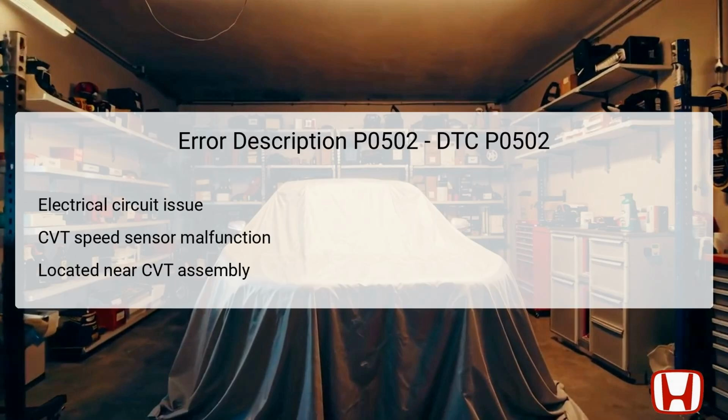The error description of DTC P0502 points to a malfunction within the electrical circuit associated with the CVT speed sensor. The continuously variable transmission speed sensor is paramount for transmitting vehicle speed data to the TCM. If this sensor does not operate correctly due to a circuit problem, it can lead to transmission performance issues. The sensor is usually situated on the transmission itself, close to the CVT assembly. Its position allows it to gauge the rotational speed accurately, which is critical for proper vehicle operation.